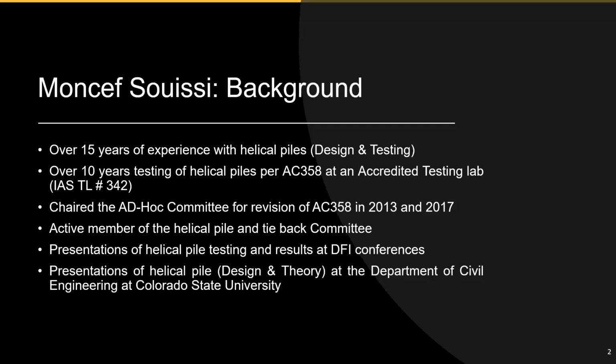So what happened with these helical pile manufacturers is they went to ICC-ES, they wanted to have an ICC-ES report, but there was no criteria at that time. That's why CTL Thompson and ICC-ES worked together with these manufacturers to produce this acceptance criteria, AC358, and that's only for helical piles. There are so many acceptance criteria. If you go to the website of ICC-ES, you will find probably hundreds of them, one for each product.